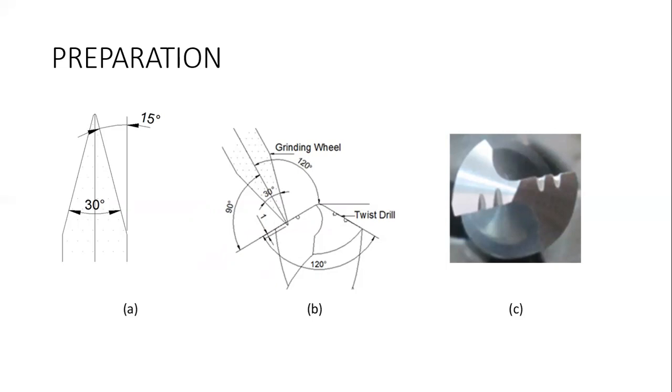The dressing and truing process is carried out on the grinding stone to ensure its sharpness and an angle of 30 degrees. Furthermore, the grinding stone is applied to make a splitting nick with a depth of 1 millimeter and a standing and turning angle of 9 degrees from the cutting lips of the drill bit.